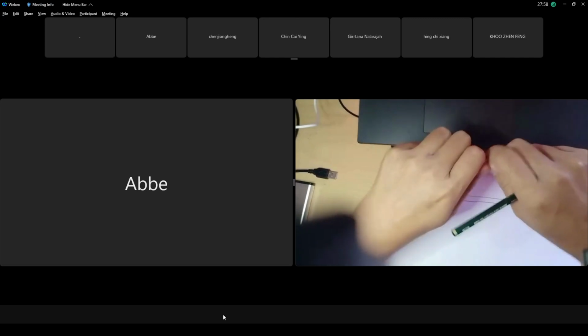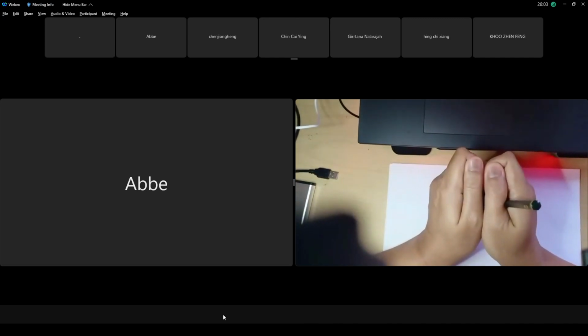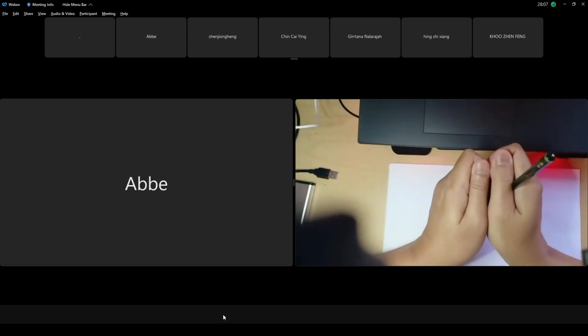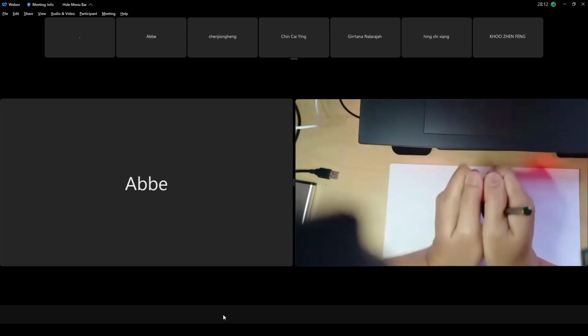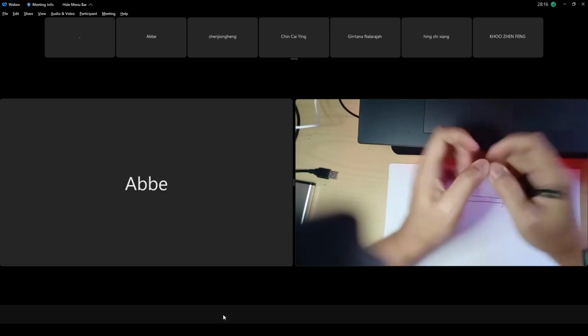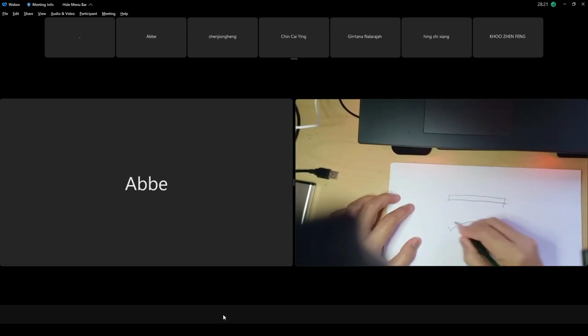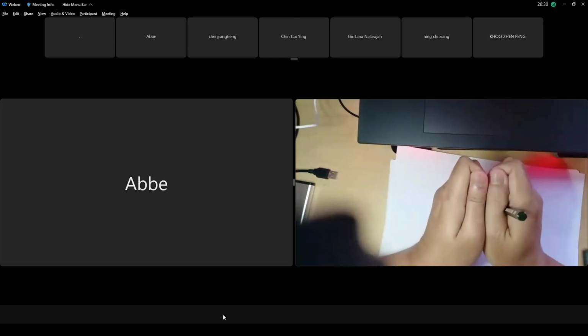Remember that if you just bend in one direction, that is static loading, because you just bend one direction. One side is in tension and the other in compression. If you just bend like that, you can never break the wire. But if you bend like this and like that, this side goes into tension, and when you bend the other way, it goes into compression. You bend like this, like that, again and again.